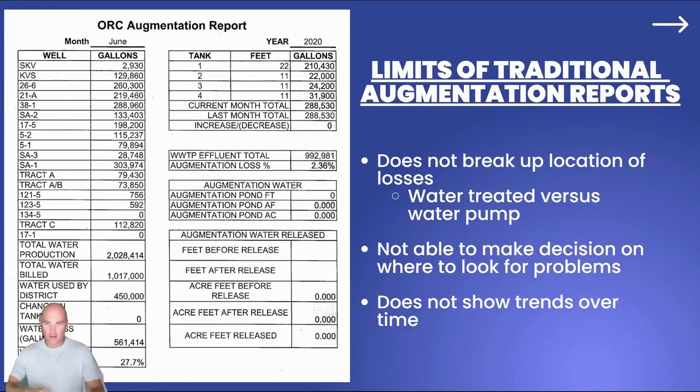But what's happening is all those wells a lot of times are located miles, hundreds of feet away. And so you're not quantifying what actually leaves the wellhead and comes into the treatment plant and then breaking those two up. So you're not understanding what you treat versus what you pump. And then once again, not having that data, it doesn't help you decide where you should start focusing your efforts to look and try to figure out where you might have a problem by sending someone out and doing field research.